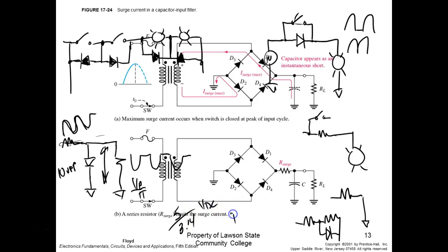If this is called R1, then I would say I would be equal to my volts DC divided by whatever R1 was, like 1K or something like that. It's the same formula that we use. It's just here the diodes in parallel.